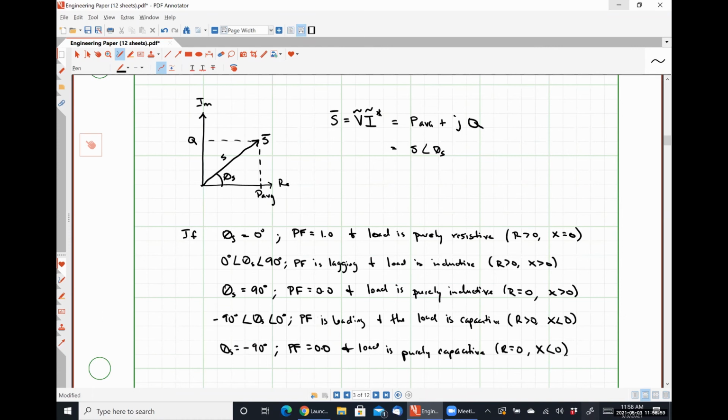Because the amount of metal that's deposited to create a wire is of a uniform thickness, we wind up dealing with a quantity that's called sheet resistance. The sheet resistance is really just resistance divided by its thickness. So for a particular amount of surface area of metal, you get a resistance. And when you put some of those squares of metal together, you can create larger scale resistances and all that kind of stuff.